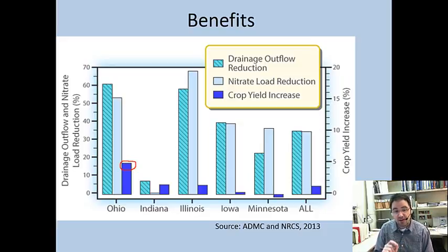Now, this is going to be very year dependent. For example, in Iowa, the data that was summarized in these, all but one of those years were wetter than normal. We had wet periods throughout most of the summer. Those would be years when we wouldn't expect much yield benefit from the managed drainage system. Because if we're wetter than normal, we probably have very little drought stress on the crop, such that having a little bit more water is not going to provide much benefit, and we didn't see much benefit.